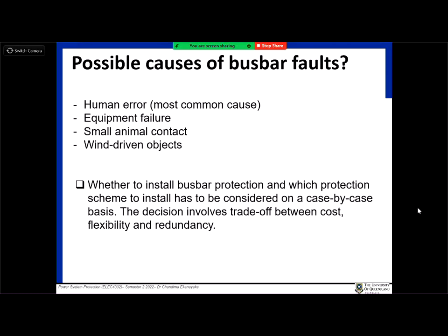Also, if a certain area has redundancy, for example the power is coming from another feeder or another substation in a sort of ring connection, then you probably don't need very high reliability for a certain substation, because another substation can look after the same area. So if the redundancy is there, you can reduce the cost as well.